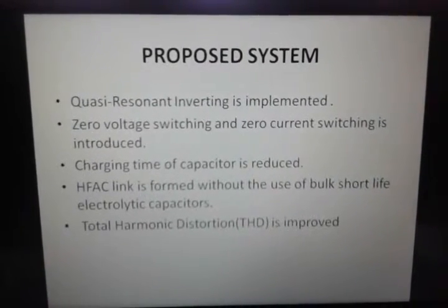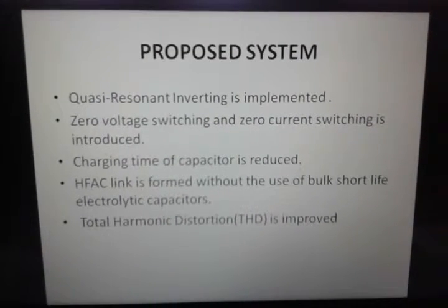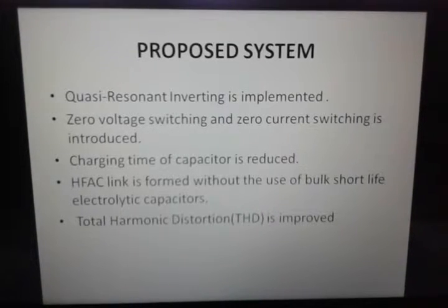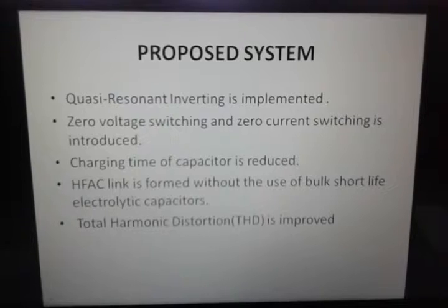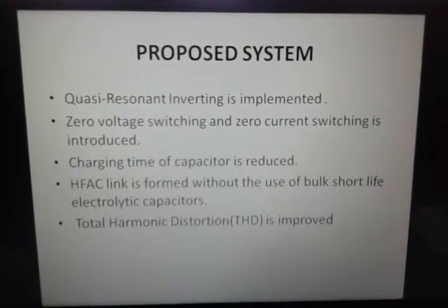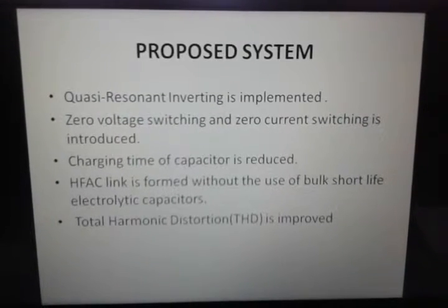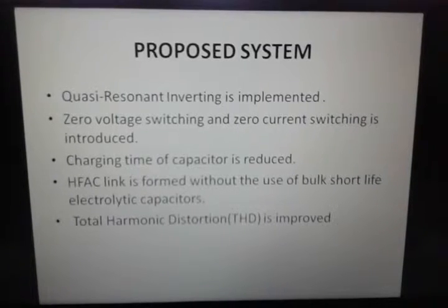It is applicable for constant load applications and it is off-time control, whereas ZCS is on-time control. The charging time of the capacitor is reduced. The HF AC link is formed without the use of bulky short-life electrolytic capacitors. Total harmonic distortion is improved.